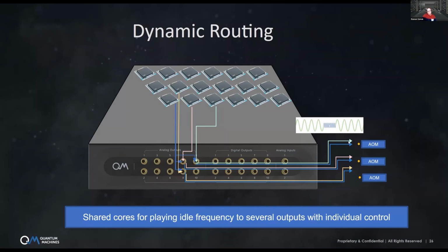Yeah, so this will allow you, for example, to keep AOMs warm. So while you play a waveform, you play it, and the moment you stop playing it, you can switch on this blue pulse processor core that will just play out of band to the AOM and keep it warm. 0 dead time, switching in between the 2 pulses. Yes, and it's also phase coherent, but in this example, it's not that important.